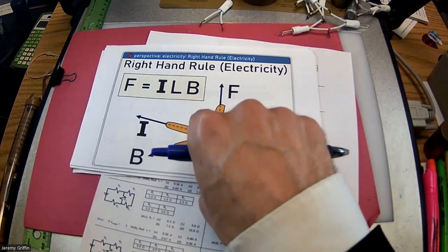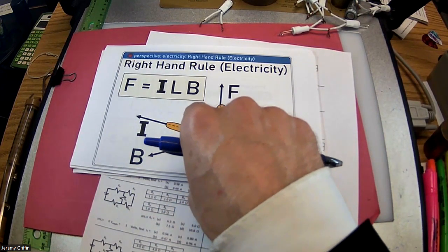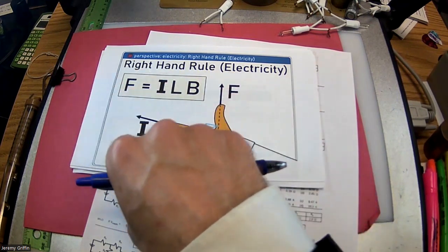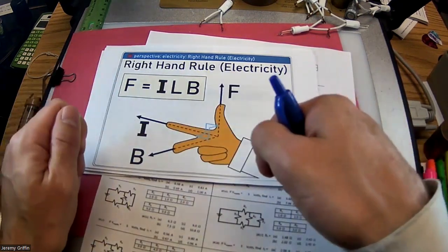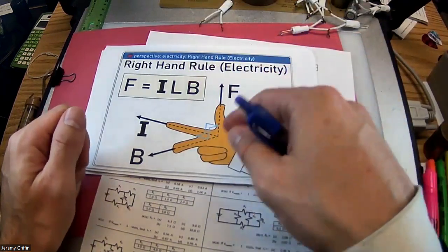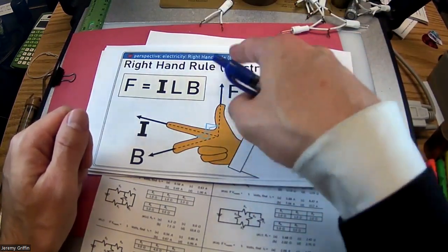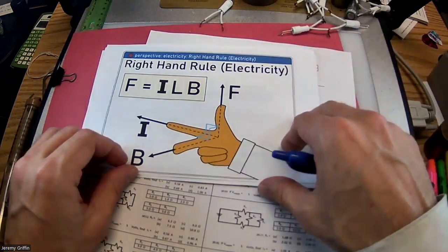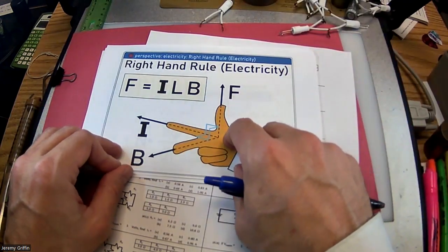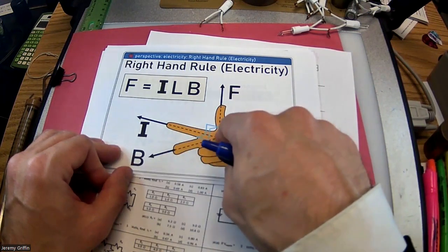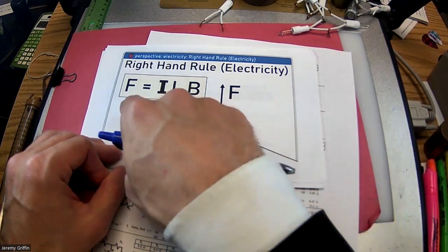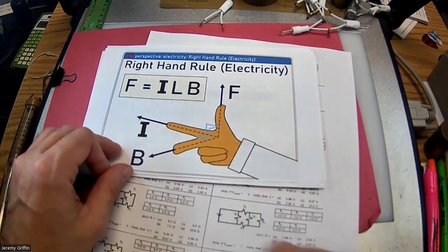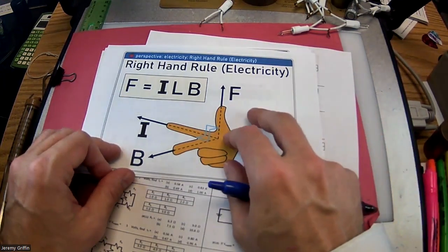If you run a current by a magnetic field, right? So if I had a wire that had some current running through it next to a permanent magnetic field, it would actually feel a push. It would push it perpendicular. And that is the principle behind motors. That's how you build a motor. Right? So you run electric current past a magnet that can cause a ceiling fan to turn. Right? And the third thing you can do is you can force a magnet past a wire, which will generate a voltage, which will generate a current. Okay? And that's what a generator is.